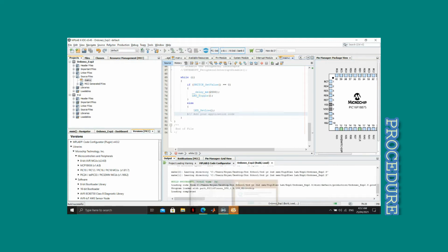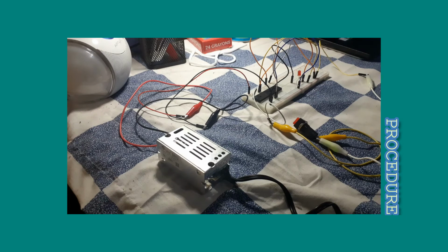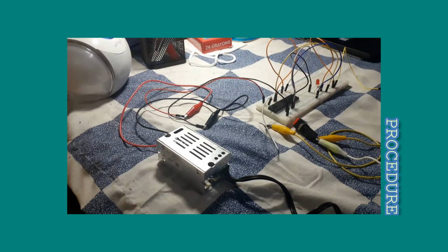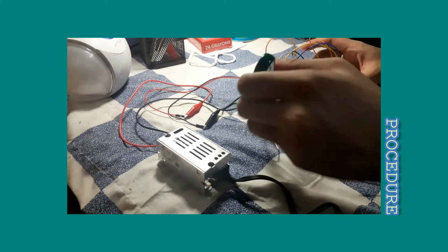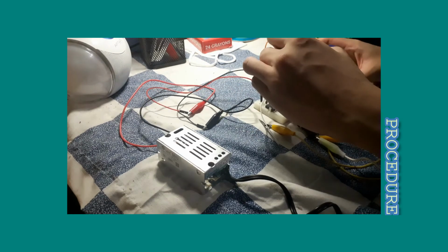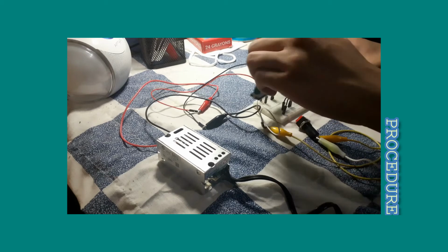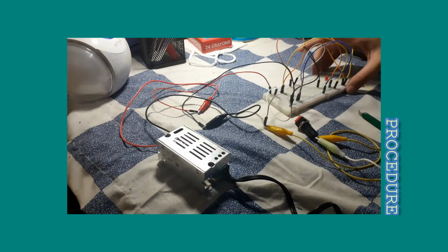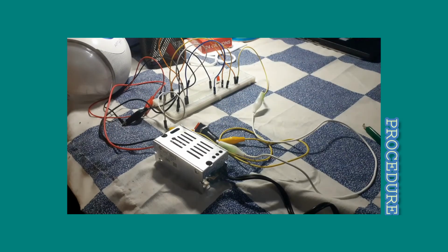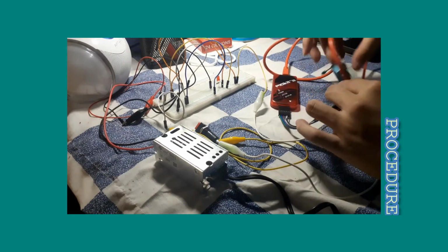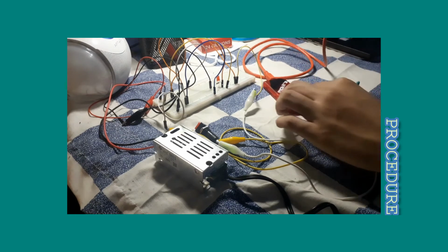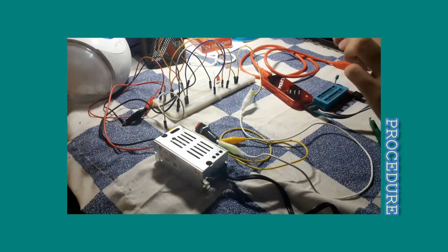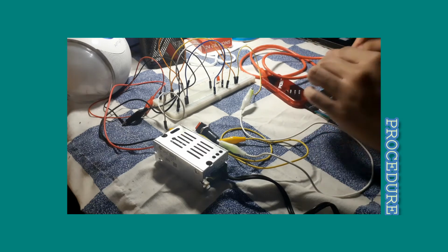It is now built successfully, so let us reload the hex file and let us now put our integrated circuit and program it. Now we would program our integrated circuit using our PICkit tool. First, let us remove the IC from our breadboard. And let's set this aside. Now let's get our PICkit, lock and plug.